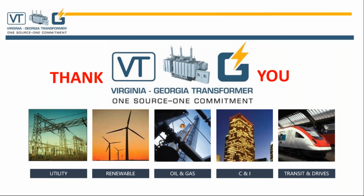If we can assure that we only operate in Q1 and Q2, where the power is always flowing towards distribution, is there a concern as long as transmission stays below 105% and at 0.8 power factor? I think if we are in quadrant 1 and 2, I don't think we will see any issue from the existing transformer, because the Q is flowing from the source to the load. But then the major question comes, if we can assure that, just like our attendee says, then yes, the impact will be less.